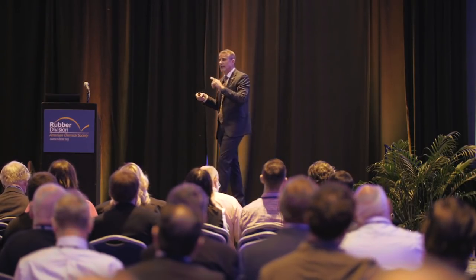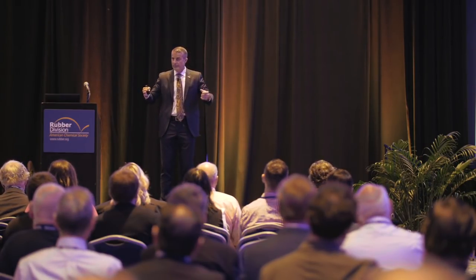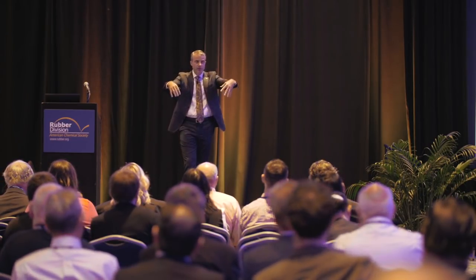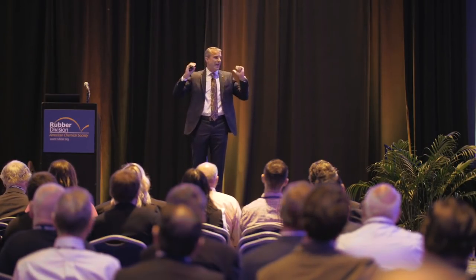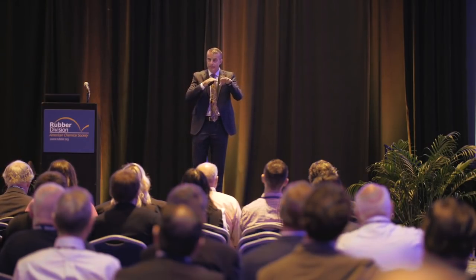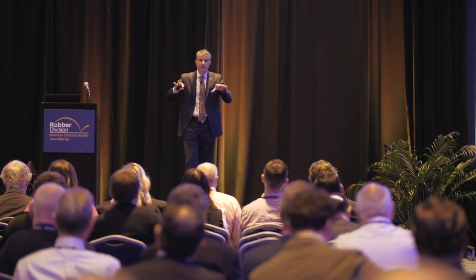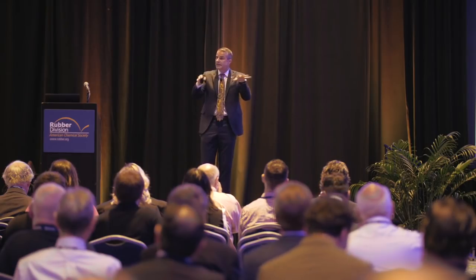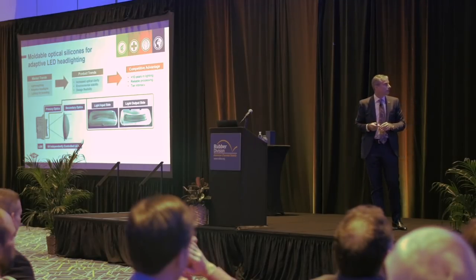I have a video now, but I would like to give you a little bit of a sense. The way this fully integrated system works, and that's why the OEM, the tier one, and the material supplier have to work together, is that you have a bunch of sensors in the front of the car. These sensors constantly look at what's going on in front of you. They feed back to those LEDs, and they'll block out certain parts, as you can see. I'm just explaining this because I think it even comes with some kind of soothing music. And then it deactivates or activates certain LED chips as you go along. So let's roll the tape.